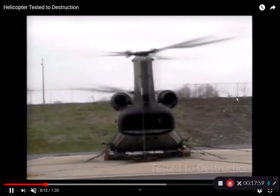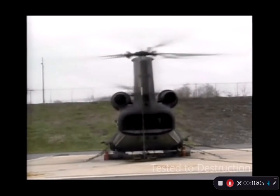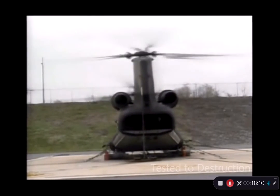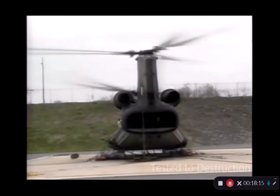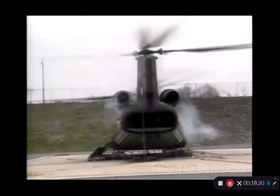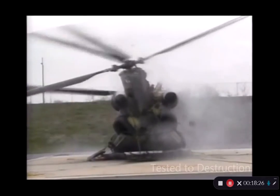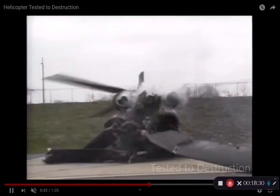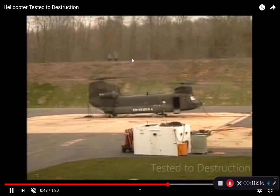All right, so in this case, we see the helicopter, as the rotor spins, it will hit a resonance of the whole structure. And it's really causing the whole helicopter to shake. The amplitude of vibration grows a lot as the forcing is coming close to the natural frequency. And you see you're starting to tear off pieces of the helicopter and rip things apart. And eventually the whole helicopter destroys itself. So all of that is due to this simple phenomenon.